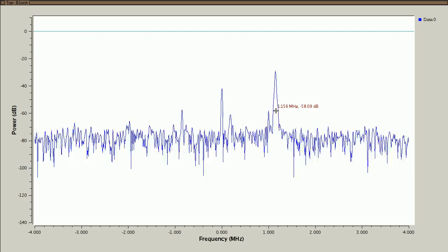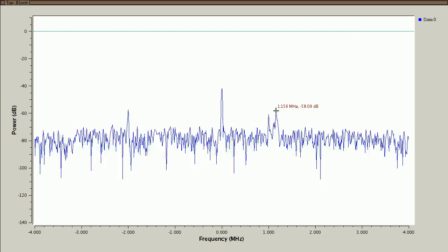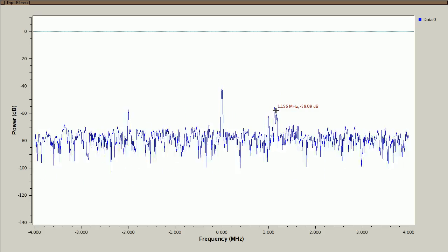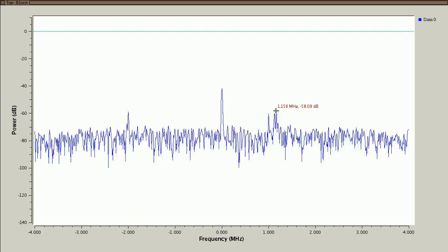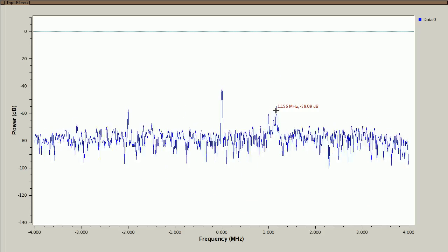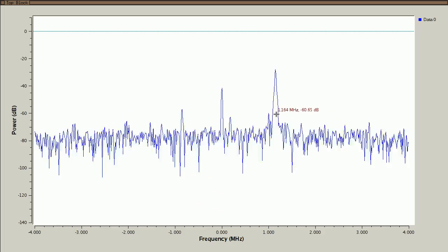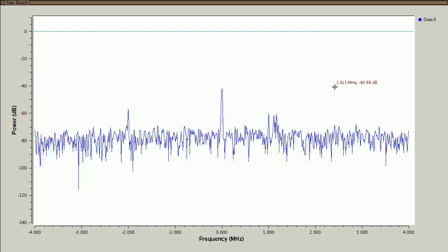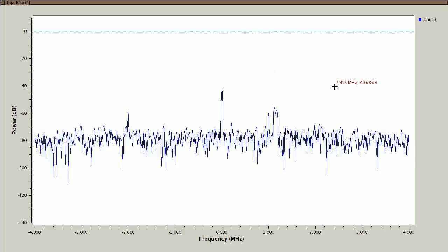If we had a very weak capture, if we weren't using very much dynamic range, then we have a fairly poor signal to noise ratio, and that means when we transmit, we're going to be transmitting a higher proportion of noise than we maybe could be. But if we were to recapture our signal in such a way that we use more of our dynamic range and have a better signal to noise ratio, then when we retransmit it, this noise here would be much lower in proportion to our transmitted signal. So we could be a better neighbor on the spectrum actually just by having a better capture in the first place.